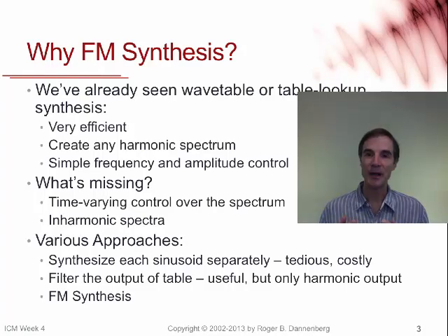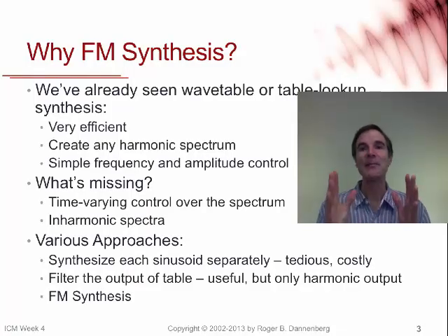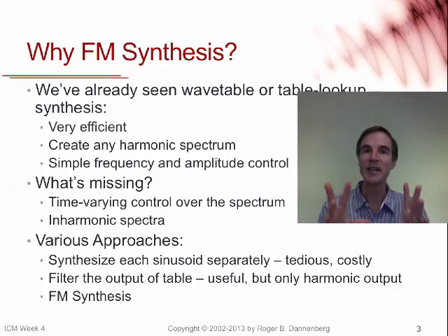If you're doing table lookup, you have a fixed table, and so the wave shape that you generate out of this table, even if you speed it up or you make it bigger, higher amplitude, it's always going to be the same shape, and your ears pick that up. It's actually a somewhat uncharacteristic property to have this invariant wave shape in the face of changing frequency and amplitude.